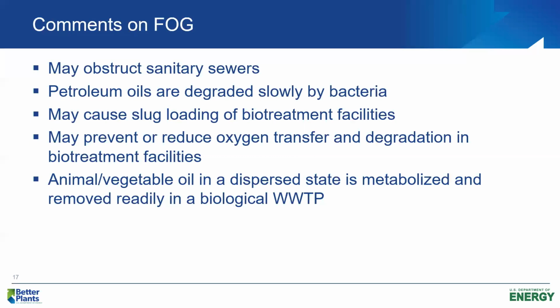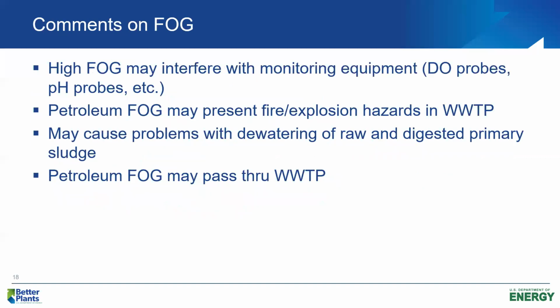Another thing, fats, oil, and grease can contribute to nocardia foaming in an activated sludge process, and that is something we definitely want to avoid. Another thing oil and grease does, if it coats DO probes or pH probes or ORP probes, it can adversely affect their performance and give us false readings, and false data leads to false decision making. And then petroleum oil and grease, under certain conditions, could be a fire or explosion hazard. So again, we've got to be concerned about FOG coming into our municipal treatment plant.